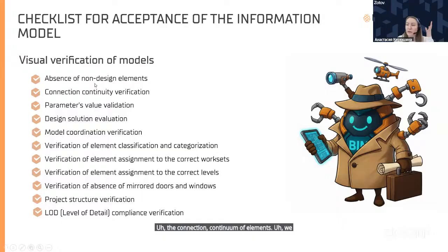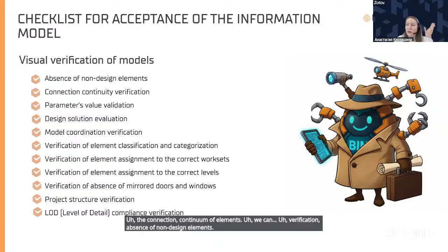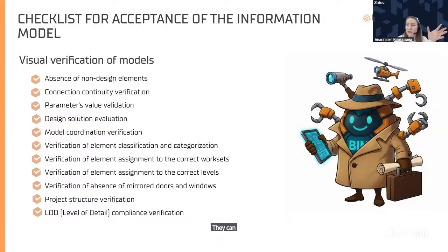We can verify the absence of non-design elements. We can check the design solution evaluation, model coordination verification, and verification of element assignment to the correct work set if we are talking about Revit. And we can do project structure verification and the LOD.